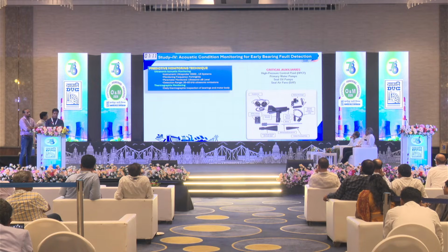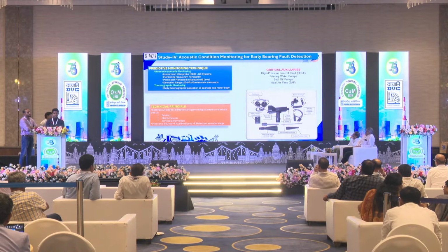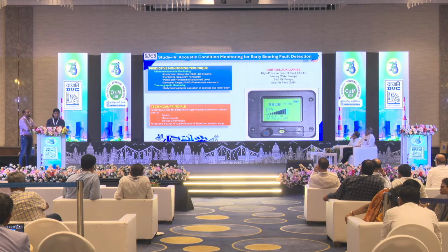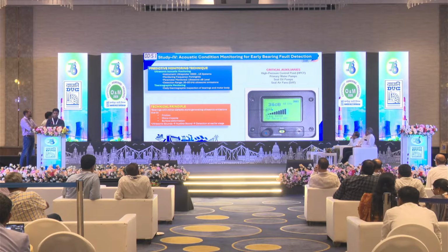To tackle this situation, we started a predictive monitoring technique. We use Ultraprobe 10,000 to monitor ultrasonic dB levels, and along with that, we also started daily thermography of the critical motors. This instrument measures ultrasonic sounds of bearings with minor defects and converts them into audible sound so that we can detect the faults at an earlier stage.